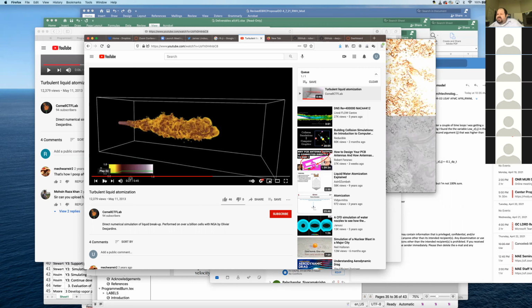I think I might have mentioned this in passing before, but direct numerical simulation actually means different things to different groups. But almost always, to the turbulence folks, it means that you are resolving all scales of the fluid flow down to the Kolmogorov scale of turbulence, which is the smallest scale of turbulence before all your little micro eddies basically dissipate due to viscous dissipation.